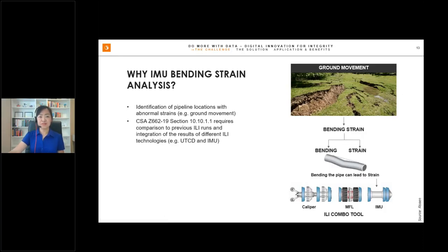The pipeline threats we are focusing on today are related to ground movements causing pipeline damage and breaking. Ground movements such as landslides and settlement, and hydrotechnical movements such as shifting or increasing water flow, can pose serious threats to the integrity of pipeline. The consequence of a ground movement event can vary greatly. Certain types of ground movements are gradual and can be monitored and mitigated before a catastrophic failure occurs. However, other forms of ground movements can occur instantaneously and can be very difficult to predict.